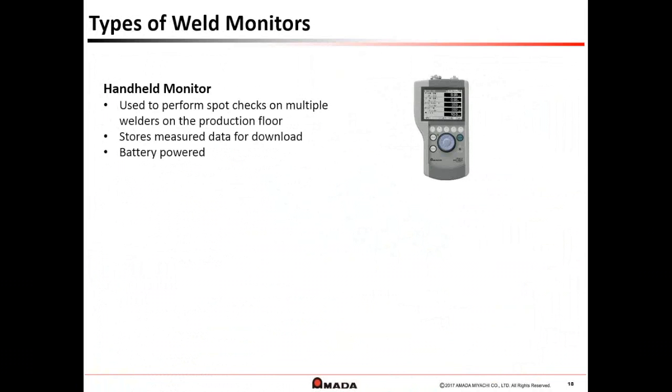The checks it can make are, obviously, it can measure the current, it can measure the voltage, and force at the same time, utilizing a force sensor. This gives you a real bird's eye view of your process, to make sure that your force is firing at the same time, with correct current and correct voltage.